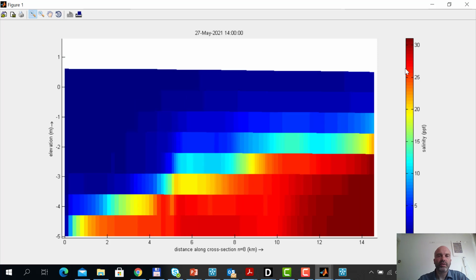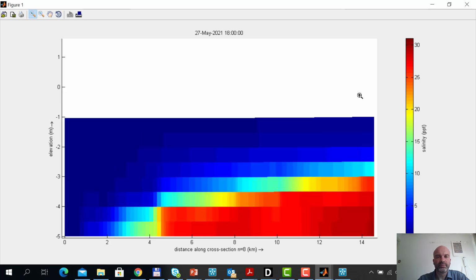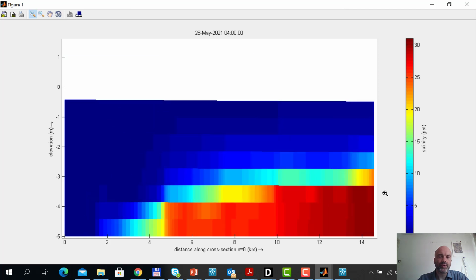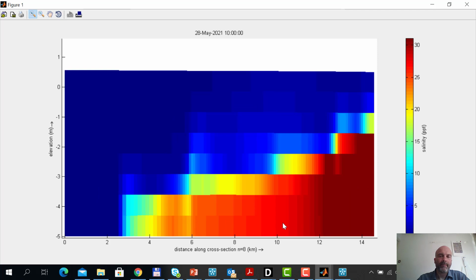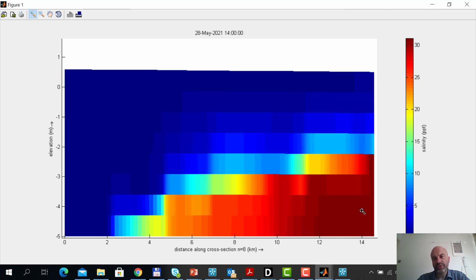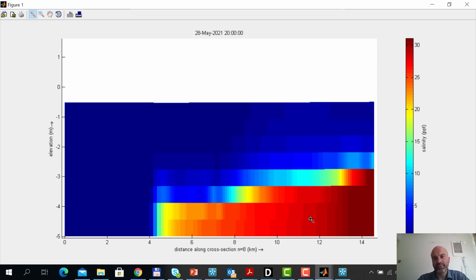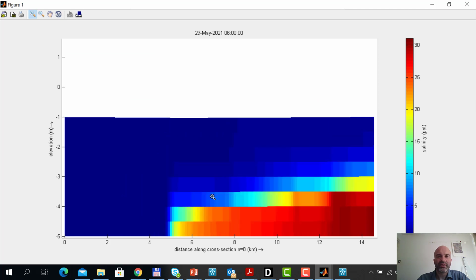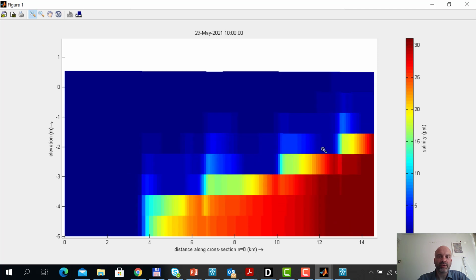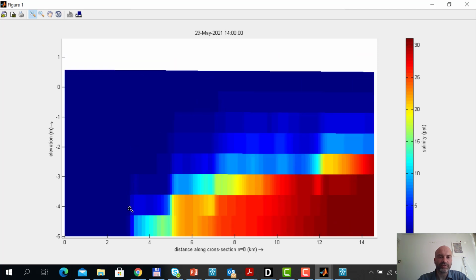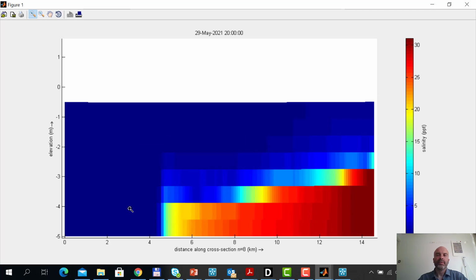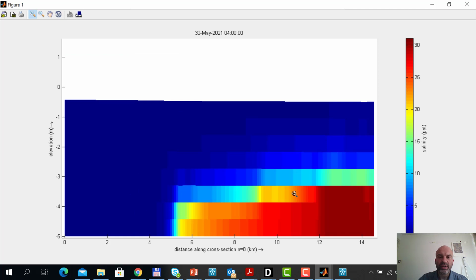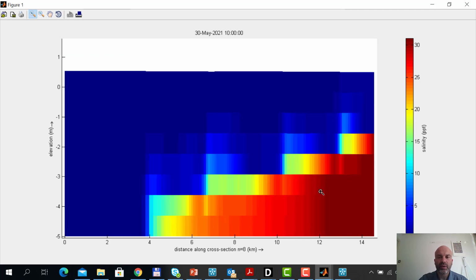You see indeed the tidal motion going up and down. You see the fresh water on top, salt water in the middle, near the bed, and you see the intrusion of salt, which is sometimes a lot, and at the end of the ebb it is limited, and then the flood comes, and at the end of the flood there is more salt intrusion. And you see indeed mixing of the salt water.